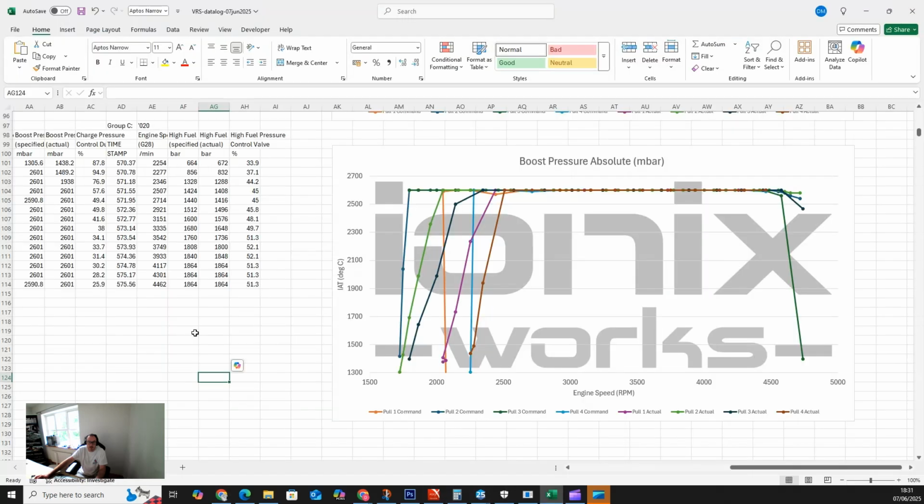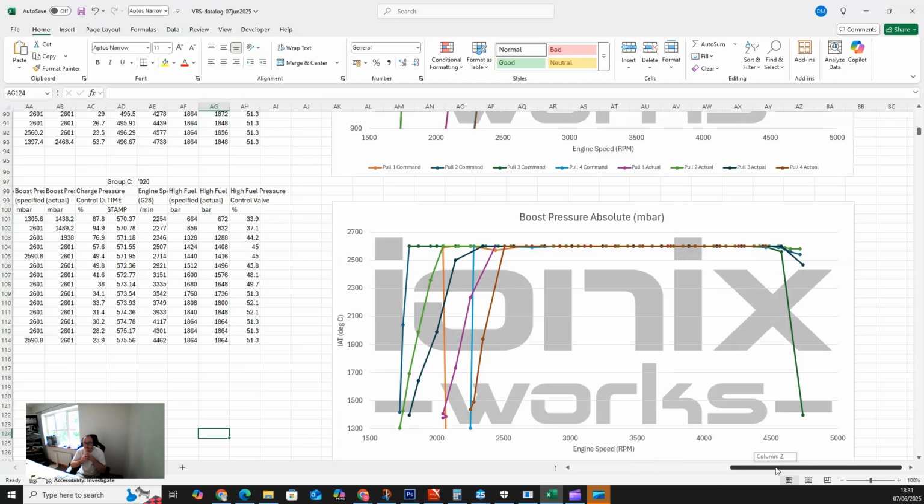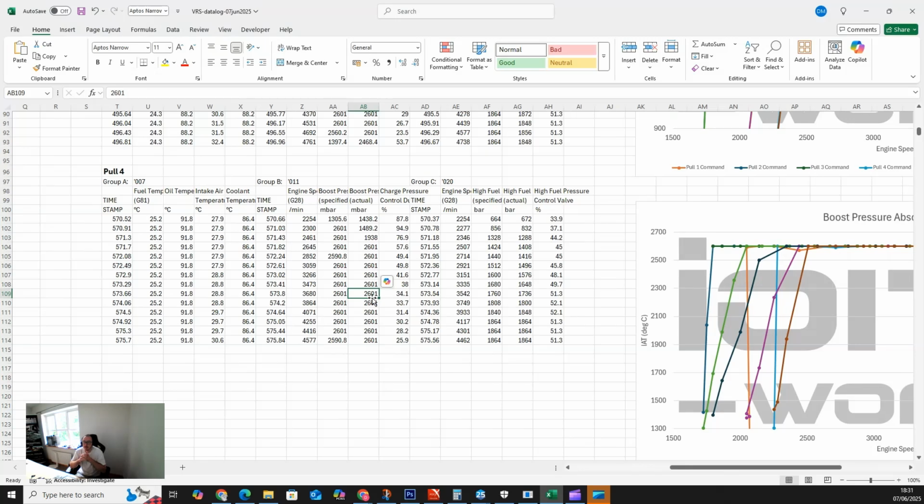Okay, so 3-bar manifold absolute pressure sensor. The A in that is key. Absolute pressure is inclusion of ambient air pressure as well. So the control units will include this, as air pressure obviously fluctuates with temperature and altitude as well. So we want to be mindful of that in all the calculations in the ECU. So we're looking at absolute pressure as opposed to gauge, which takes out the ambient air pressure.